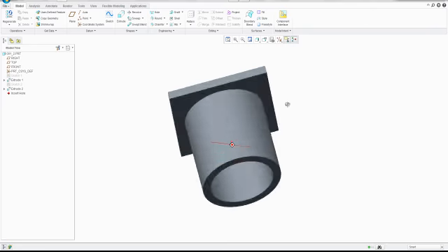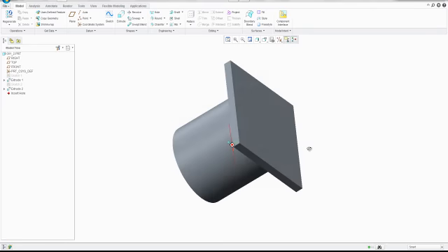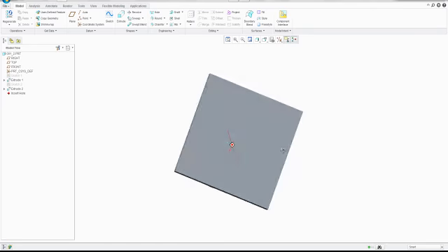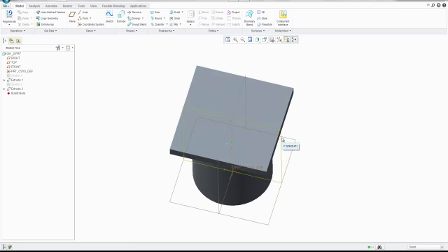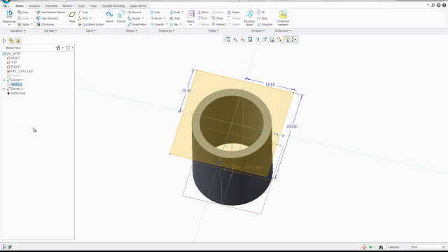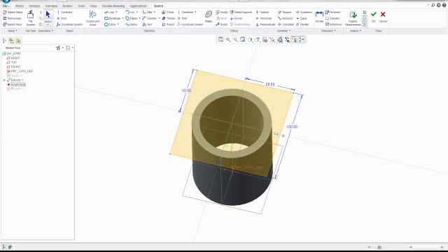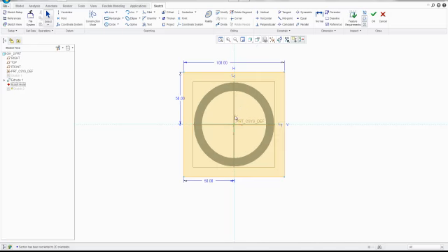I did not do that in my sketch, which I could have. So what I want to do is, rather than creating a new sketch and extruding and removing material, I want to redefine the sketch that I've already created, and I can do that by going into Sketch 2 and editing definition. Okay, I'm going to go ahead and reorient my sketch plane once again.